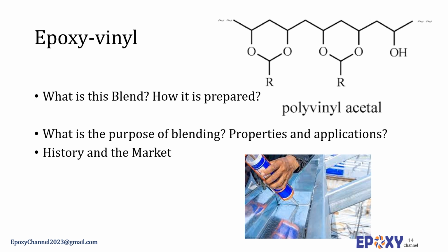The solubility of the vinyl polymer in the epoxy resins will depend on the molecular weight and the grade of vinyl used. Polyvinyl esters can be dissolved in liquid epoxy resins that are heated to about 100 centigrade, or in melted solid epoxy resins. However, most epoxy vinyl blends are normally prepared via solvent solution. The formulated adhesives are generally available as films or solvent solutions. They are commonly used as laminating adhesives for film or metallic foil because of their high peel strengths.